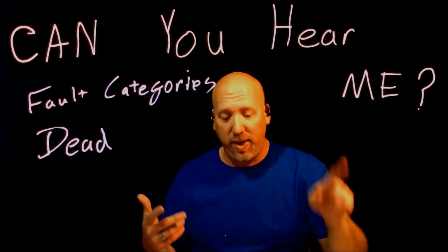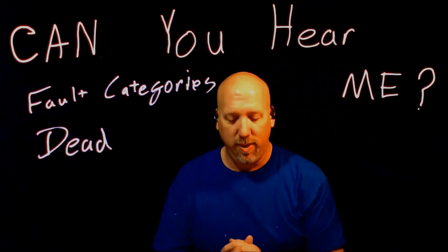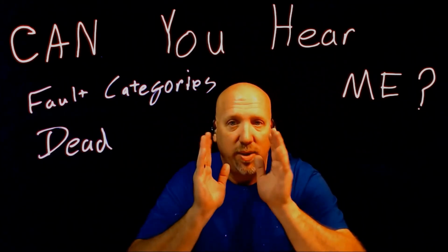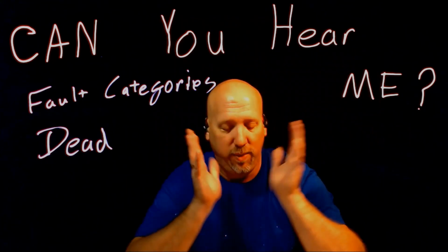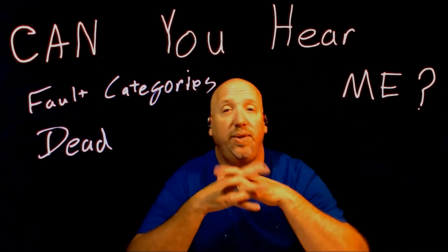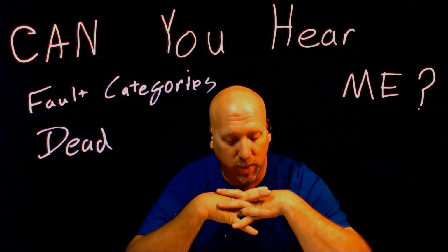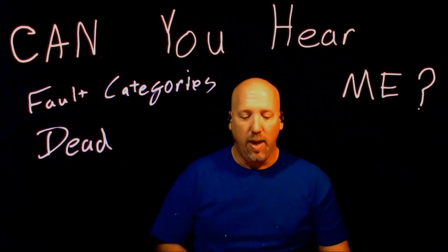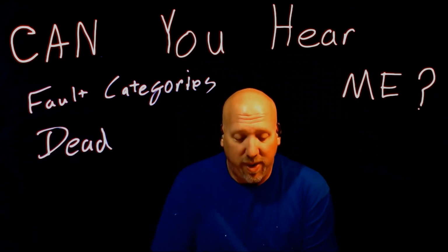So if you have a ring network, or a loop network as it's called, and there's no short found, here's a strategy. I've got no shorts. Everything's not working. What's happening here? If your testing reveals there's no short, but you still have no communication with the system, you probably have a gateway managing traffic.